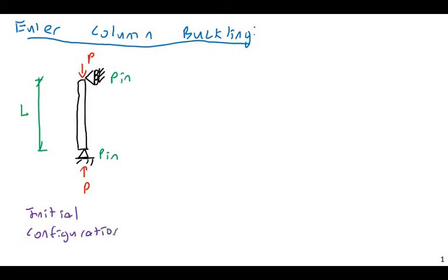And we, of course, know that after it buckles, it's going to bend more like this. You've probably learned about buckling in mechanics of materials. You know that when something buckles, this is not necessarily a material failure. It's not that you're taking the column all the way up to the yield stress, for example. Rather, you are taking it to a point where the geometry itself becomes unstable and it buckles to the side, either in a C curve for single curve buckling or maybe an S curve, et cetera, and we'll talk more about that. But I'll just concern myself with the first buckling mode, where it's just buckling out like this.